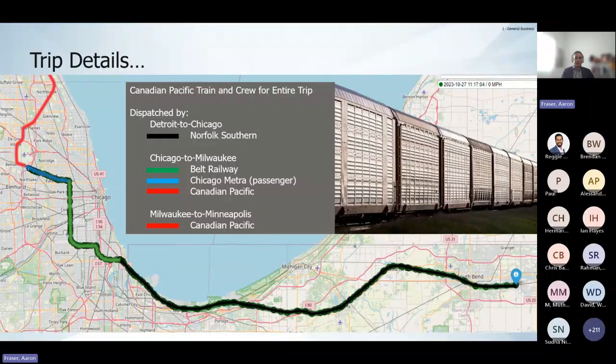So how does interoperability allow that train to traverse through the network? Well, the onboard equipment on the locomotive continuously communicates with back office infrastructures for each of the railroads, regardless of proximity to that territory. As that train traverses the network, it talks to all the wayside interface units along the route, regardless of their affiliation with a particular railroad or subdivision. And all of this obviously is enabled through the use of the interoperable train control specifications, as we discussed on the previous slide. So the system allows for any combination of crews, owners, and operating railroads to seamlessly operate over borders and through different operators throughout the United States.